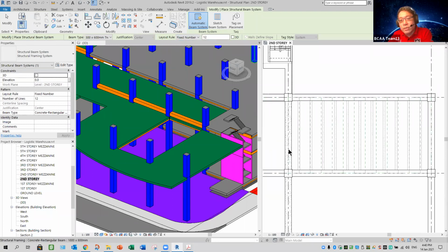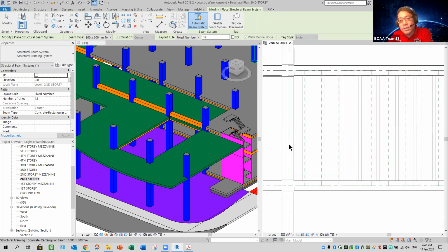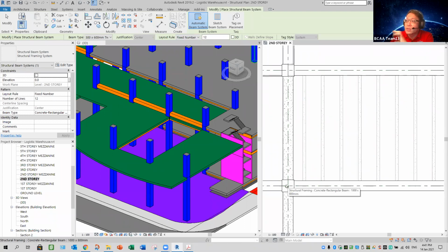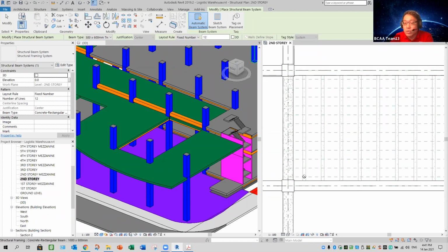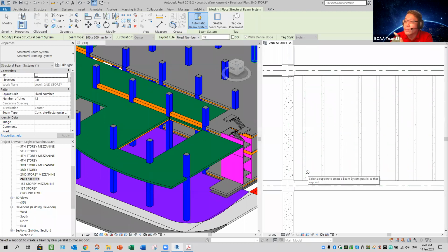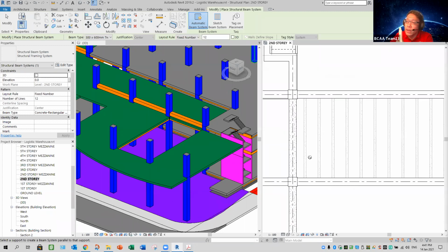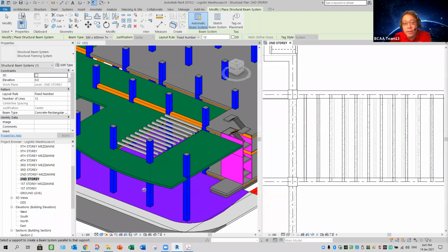So for calculation, you got to select center. Sometimes you prefer to sketch. You sketch it out based on a line or based on center. As I said, for calculation wise, always center to center. For just a construction model, you sketch based on the beam edge. You do the sketches. Always remember. All right. Clear? But here we accept both. I accept both, make it easier for you guys. So if okay, you select, it should be added for you.